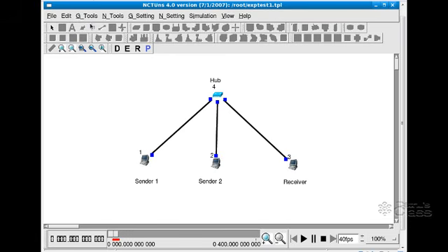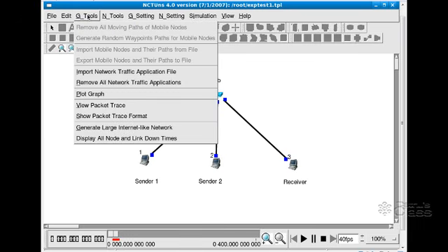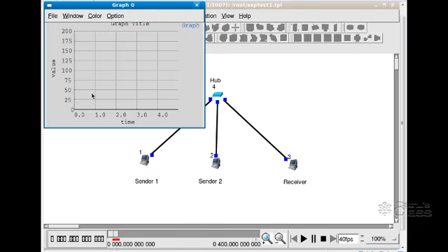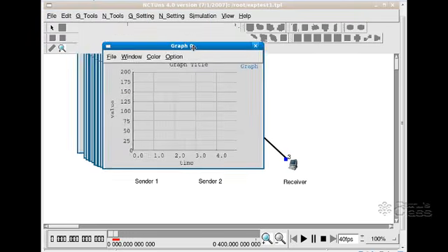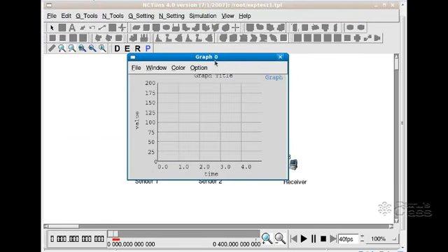So first I will show you the graphical way of analysis of the network performance. So go to G tools, click it, and click on plot graph. A graph tab will be opening up. So see here, it is time versus value, and we need to give the graph title. So here it is 0 to 4 means basically 5 seconds it is, but we have run our simulation for 20 seconds. So we need to modify the graph settings.